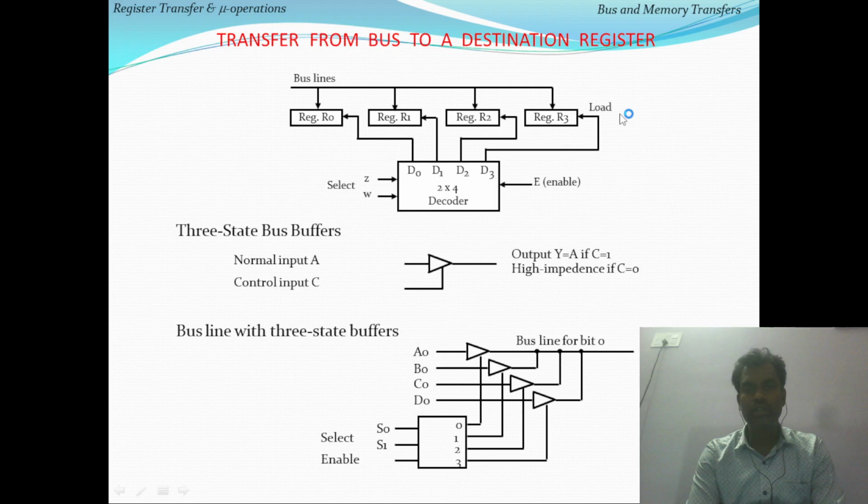So here we are using control or decoder logic that will generate only one control signal high, and the remaining are all zeros. So here I will select the register, destination select. The source select is represented with the mux select line, and the destination register is represented with decoders.